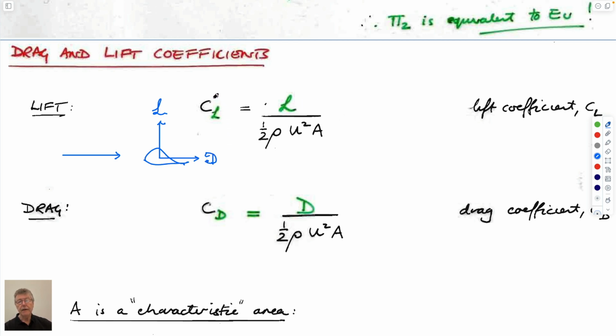And we expect that we have these values available to us from charts or from some kind of reference table. So long as we can get these, and that they're at the right Reynolds numbers, then if we know what the forces are that are being applied in our system, the weight of a guy dropping out of a balloon-carried pod, or a grain of soil dropping through water, you can get the velocity from that. If you measure the velocity of a grain falling in water, then you can solve for the dimensions of the grain. It's just a different way of doing it. But this is what external flows are all about.